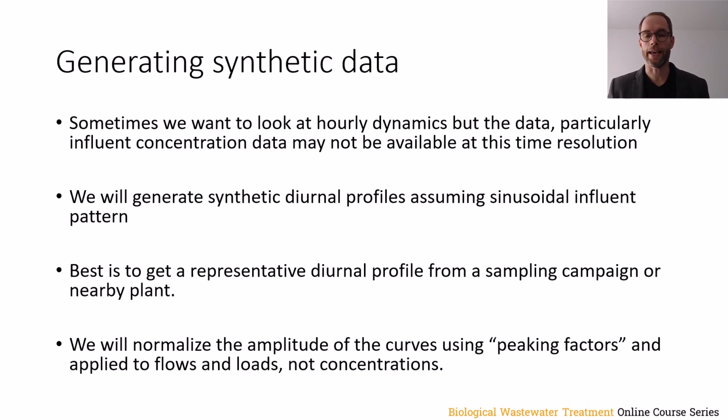We will normalize the amplitude of the sinusoidal curves using peaking factors, and this is an important term to have as part of our jargon or our nomenclature, the notion of peaking factors. And they will be applied to flows and loads, not concentrations. That's also important to know, that we're trying to maintain continuity of average flows and loads between steady state conditions when we simulate daily dynamic data, or when we simulate hourly dynamic data. We want continuity of the average flows and loads, but not necessarily the concentrations.